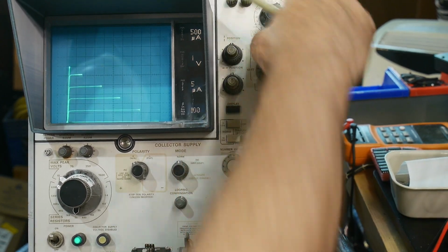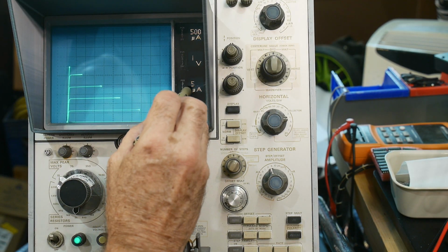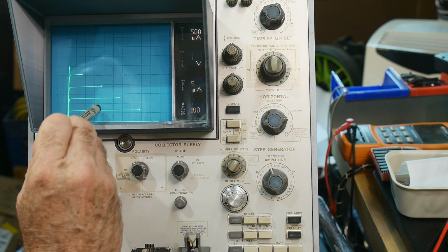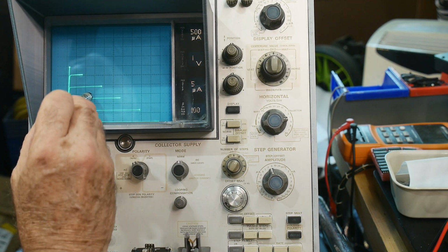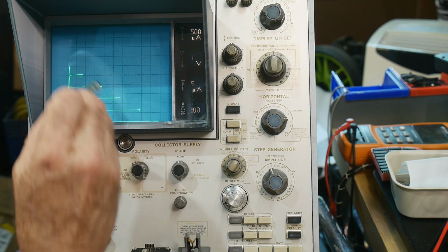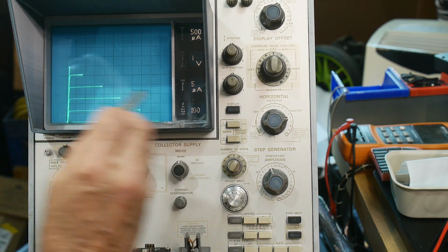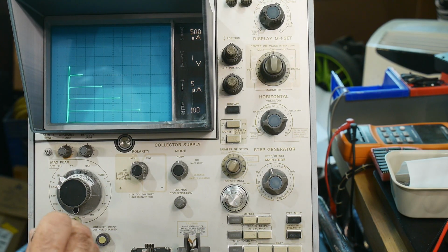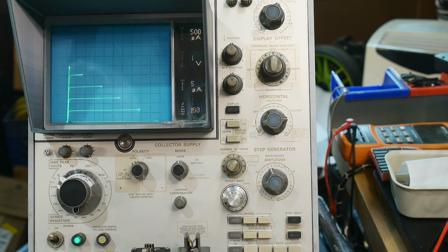Okay, so in this particular instance, we're changing 5 microamps. So this is 5 microamps, there's 10 microamps, 5, 10, 15, I'm sorry, and it's wiggling up and down. Our voltage is changing quite a bit, and that's because I'm using a 3K resistor. I set it to 3K, and so you're getting a bigger voltage drop across a bigger resistance.